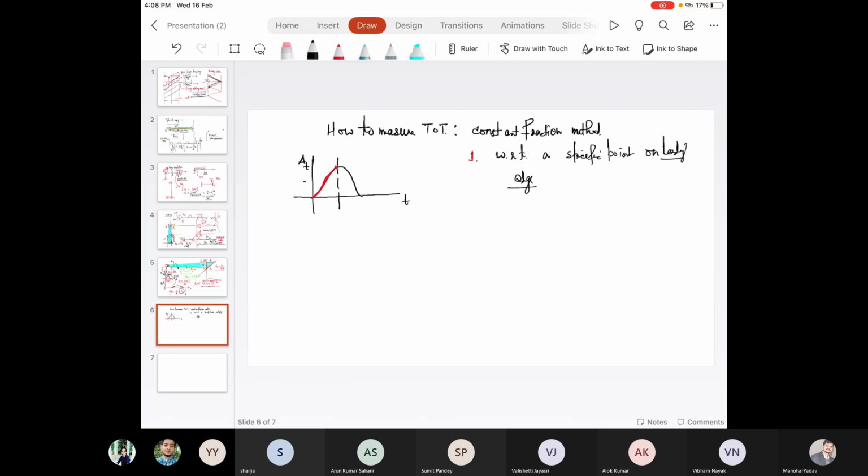So what we do, we define a specific voltage level. Let's say this is V threshold. We define a voltage threshold level that is generated at a certain level over here. Fine. And at the rising edge, when it intersects at this point of time, a trigger signal is generated. What is the role of the trigger signal? To start counting. It is used to initialize the time counter, and it is initialized.